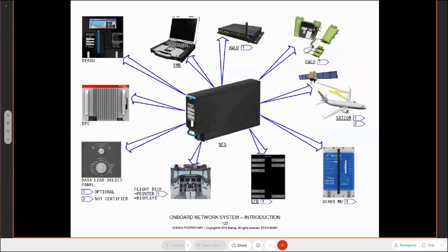There are firewalls inside here to protect the individual systems. The hard drives, which are located inside the network file server itself, are partitioned to provide some kind of security. For the wireless options, we have the airplane wireless LAN units and the crew wireless LAN units. The airplane wireless LAN unit primarily connects the aircraft automatically to what we call gatelink via Wi-Fi technology. When the aircraft touches down, it has to be on the ground, and you have to have the gatelink capability at the airfield. The system will try to locate the wireless network, and it will connect itself.